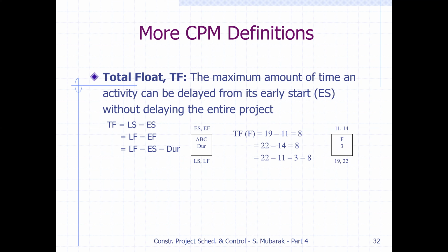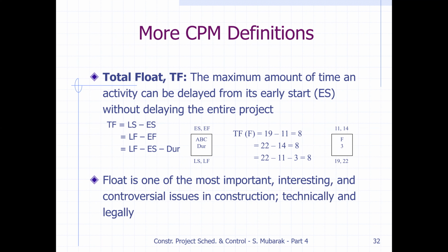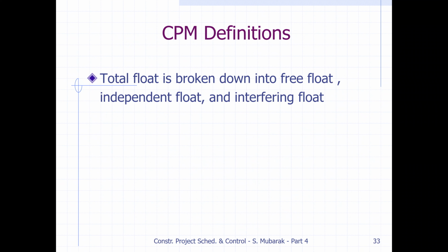So all the way, we will get the same value if we are not dealing with interruptible activities. We will discuss those things later, inshallah. Float is one of the most important, interesting, and controversial issues in construction, technically and legally. Usually the owner of the float is the contractor, but sometimes the owner or a consultant wants to use it, and they have to sit together and decide who is the owner of the float.